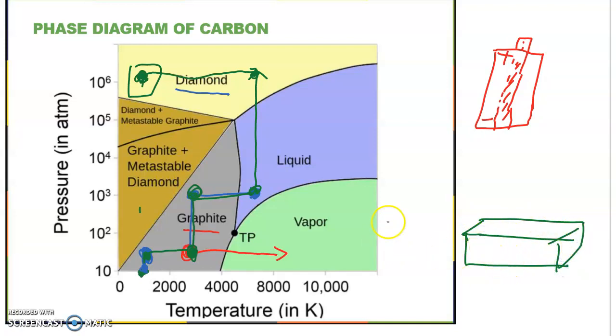How can we do it? We have to use something with a higher hardness in order for us to cut this metal. And diamond is known to be one of the hardest materials on earth. The others can be silicon carbide and some more, but diamond is one of the hardest. That's why on the saw blade, let's say this is the circular saw blade, it is coated with artificial diamond. So when the saw blade rotates, it can cut the metal.